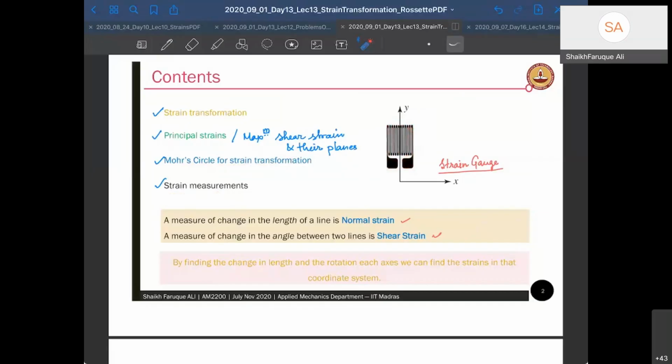When you connect them with the power output, you get the voltage out. We'll discuss this a little bit more in the next class. But this is a material in which you get an electrical circuit, so that when the material gets strained, it provides electrical voltage output which you can tap, and from that voltage you can calculate the strains. So that's how a strain gauge works, roughly.